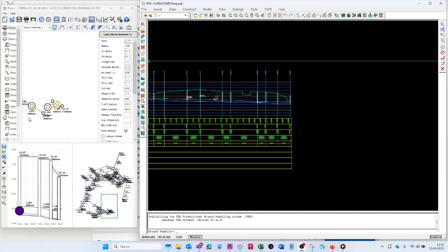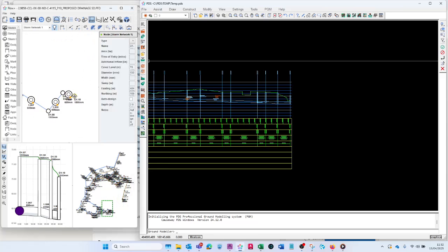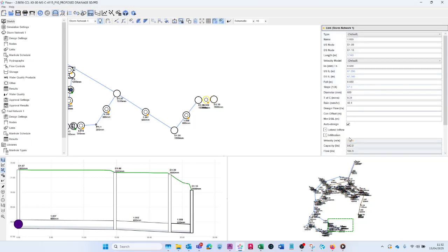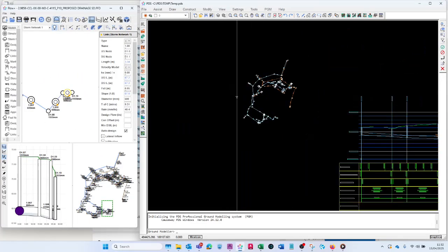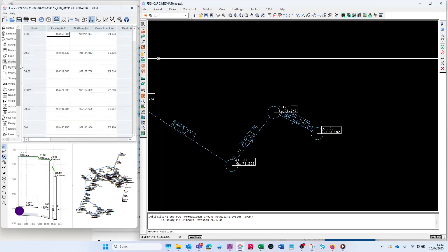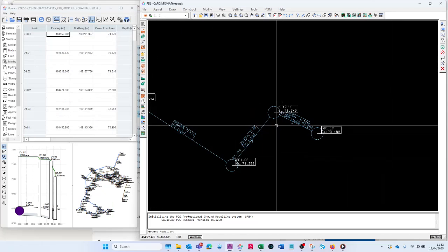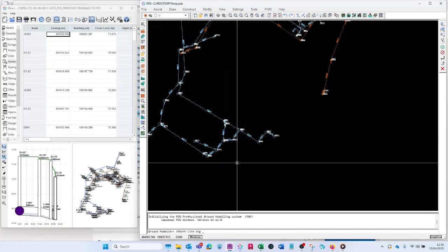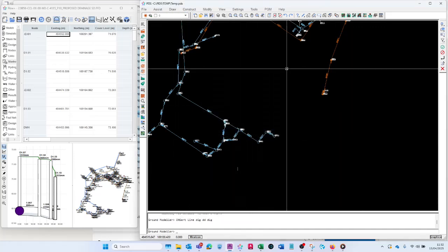Let's go to the plan and let's say, let's make this even smaller to there. That is now 3 meters. If I go back to our drainage, if I save this in flow, if I save it again, there I'm trying to go to other areas, so it's automatically saved. If I'm in ground model on this, say I want to draw a line there, drew a line. This does not update.